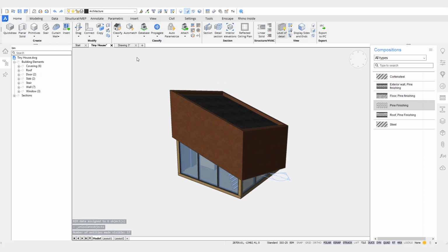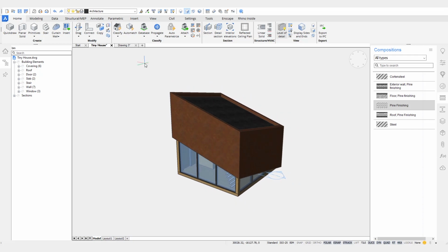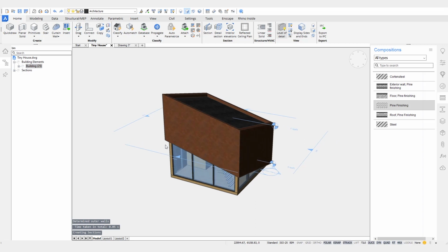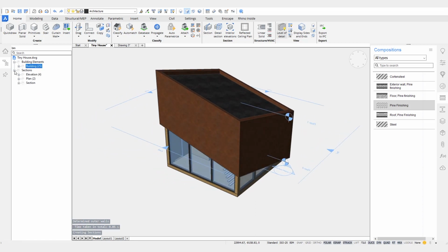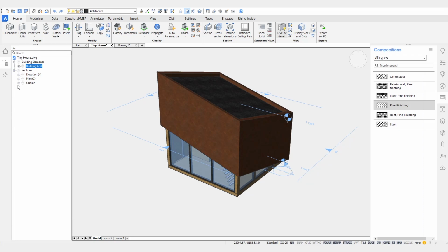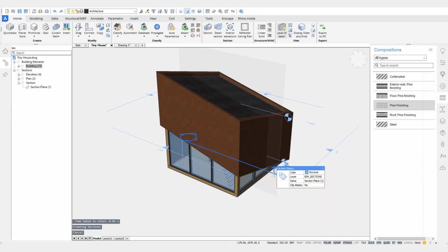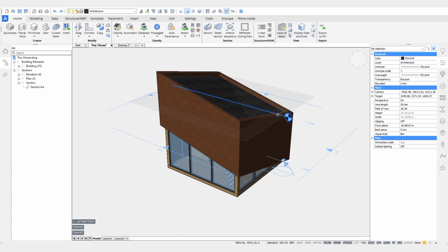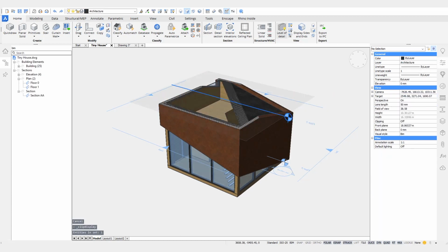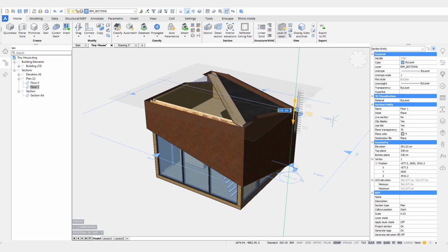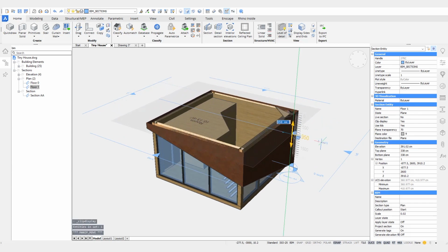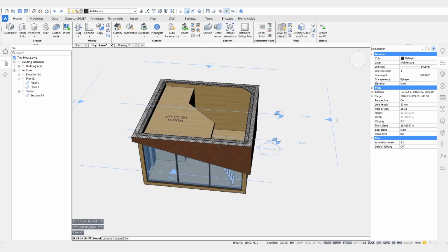And now I want to take a look at creating some drawings. We have a tool that does this automatically. It's called Bomify. It will classify objects automatically based on its geometric features. So you may think I don't need Bomify anymore because it's already classified, but actually Bomify does more than that. It also creates spatial locations and assigns objects to these locations, so buildings and stories. It creates sections or elevations and floor sections, things like that, rooms. It also created these two floor plans, or floor plan section planes. One for the ground floor.